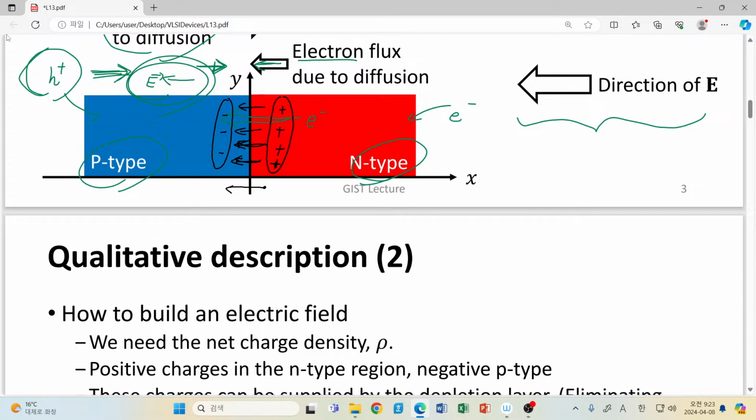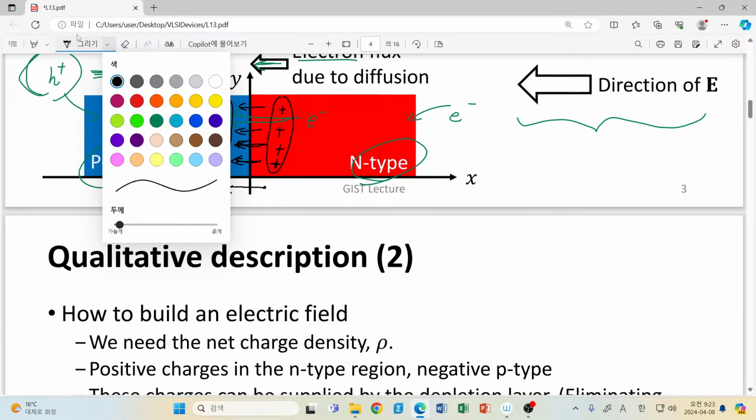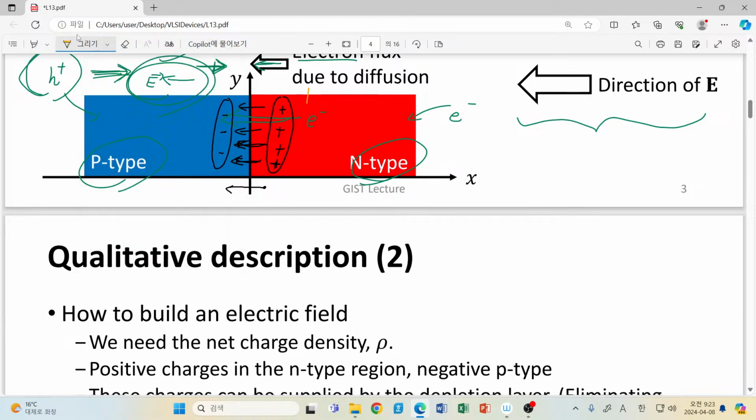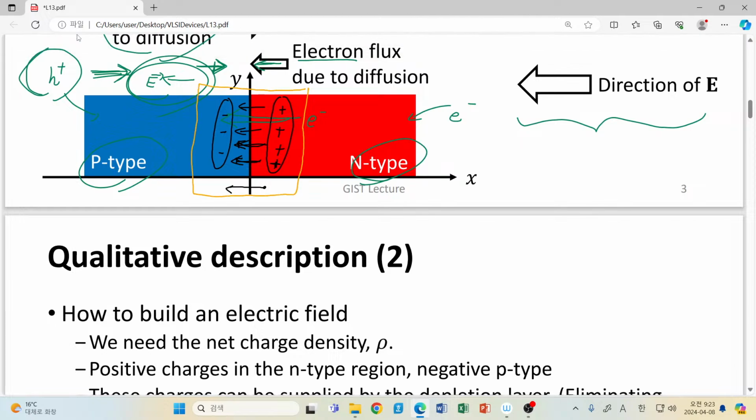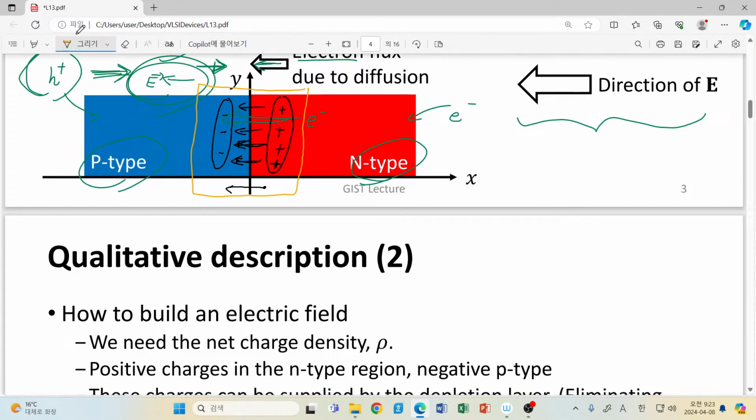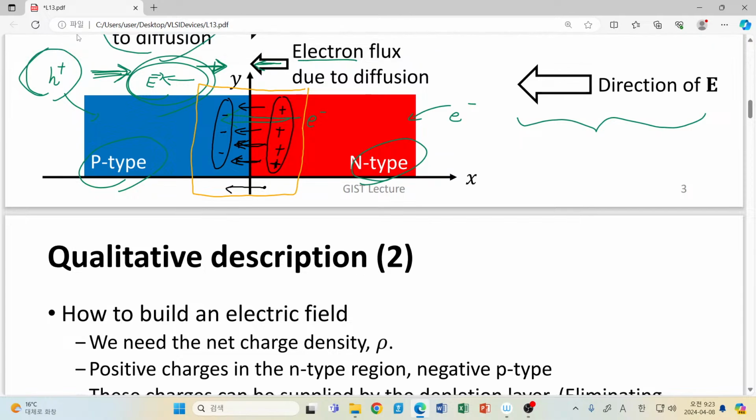When we consider a system surrounded by this overall system, inside it the net charge density is no longer 0. We have a net positively charged region. That means we will have a certain outgoing flux, electric field out of this center part. It means that without balancing this charge density, we will have a non-zero electric field far from that junction.